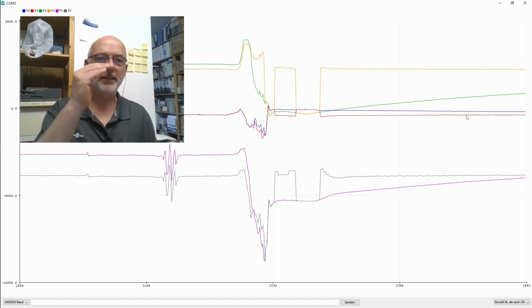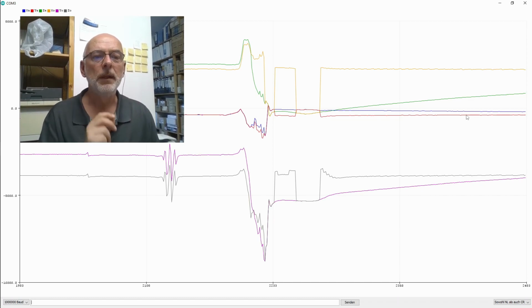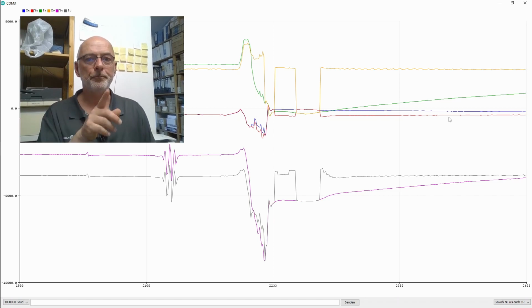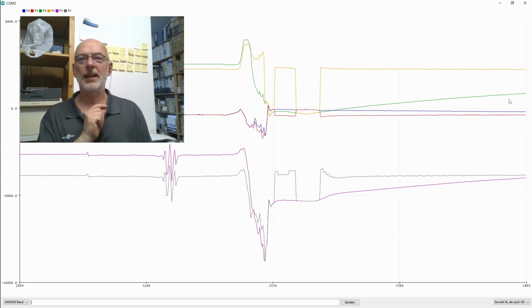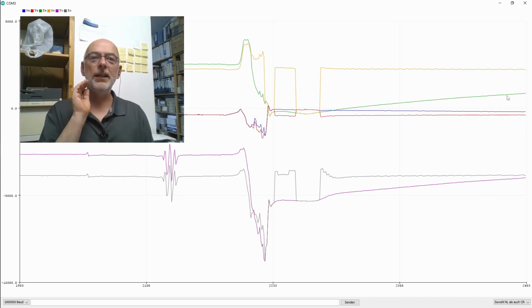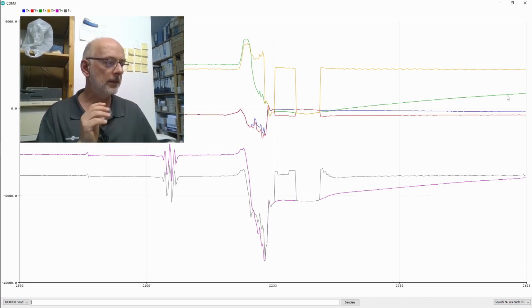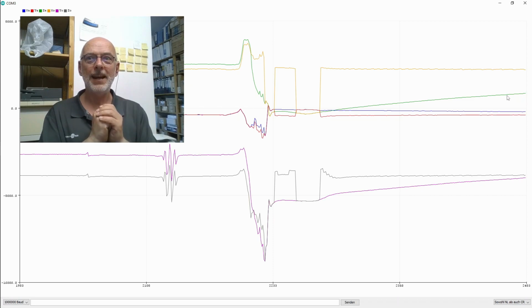We don't see much action here on the X channel. You remember that graphic, the X channel temperature offset, and the X channel is a little bit meh, not so nice. But you can see the same effect here on the Y channel. So that yellowish line here, that's the compensated curve. And after the disturbance is over, it's unfazed. It just continues on. While the uncompensated curve here, it goes also through that disturbance. And then it only slowly recovers after the temperature is rising again. So yeah, we successfully temperature compensated or offset compensated our little chip here. Great.